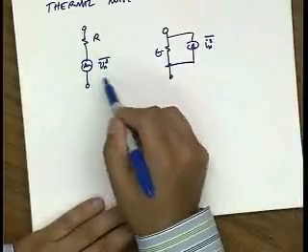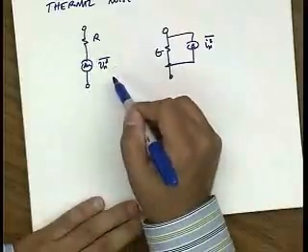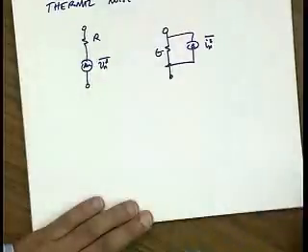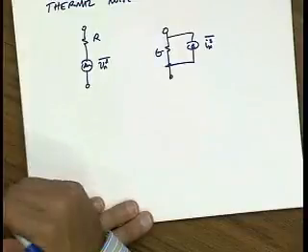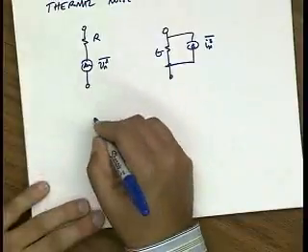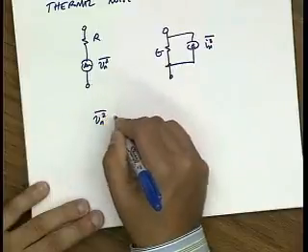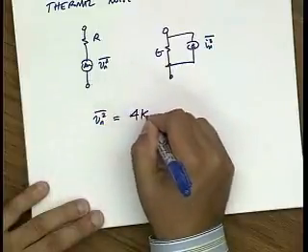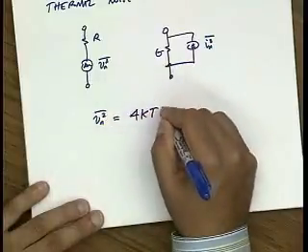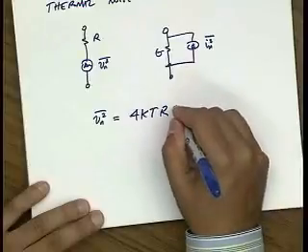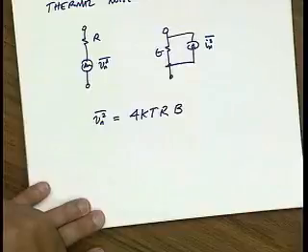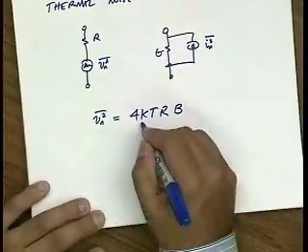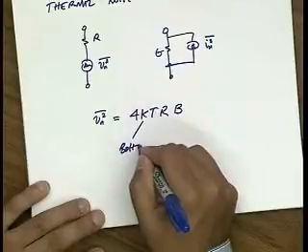If you see someone carrying around the phase of the noise voltage, you know they're fooling themselves, because at the end of the day it doesn't really matter what phase it is. It's totally random. Okay? And so Nyquist proved, using thermodynamic arguments, that the RMS value, the variance of this noise voltage, is the famous 4kTRB. So kT, this is Boltzmann's constant.